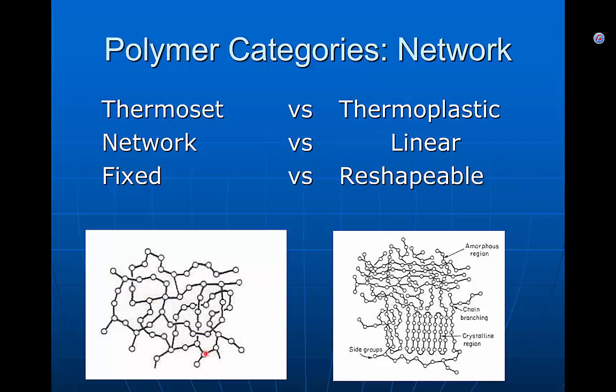And basically I can get anywhere on this molecule and I can go anywhere else in this whole molecule without leaving the molecule. The chain, this is a 3-dimensional molecule, it's all connected together. In thermoplastics, the molecules cross over each other, but this chain here, for example, does not connect to any other chains. It's a chain by itself. Now, chains can do funny things. They can fold back into tightly packed regions of what we're going to call crystalline regions. But the interactions between the molecules are some variation of a van der Waals bond and then entanglements, which can occur.